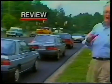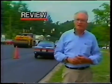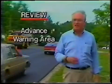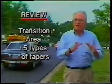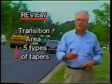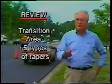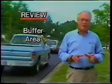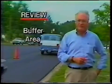Now, as a review, these are the 5 parts of a traffic control zone. The advance warning area alerts the driver that there's something ahead that demands his close attention. In the transition area, traffic is shifted or moved to eliminate interference with work activities. The length of the taper should be computed or obtained from a table. The buffer area provides a margin of safety in case a vehicle runs through the transition area.